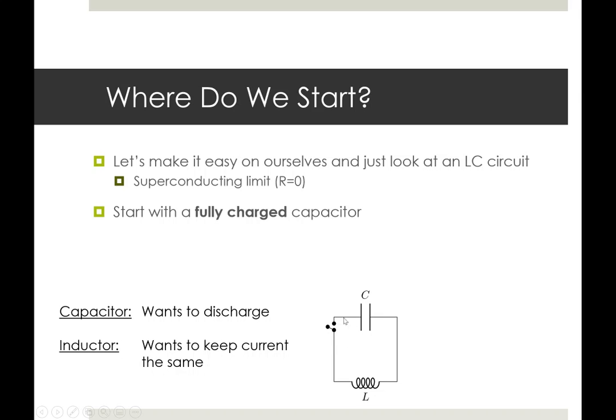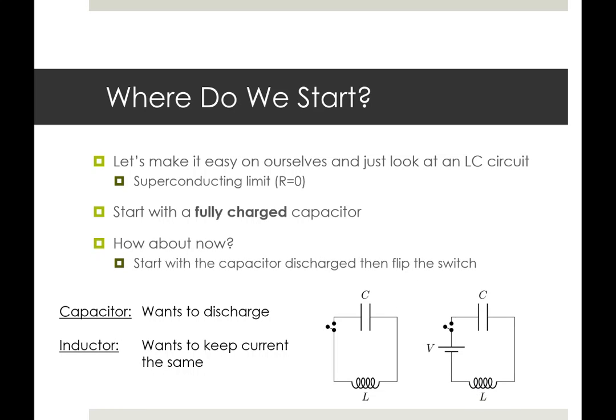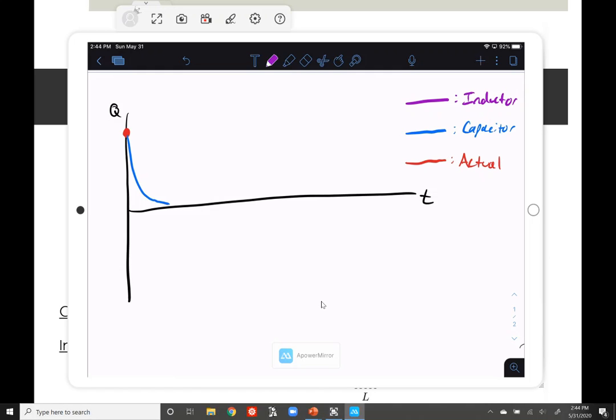Initially, this was an open switch, absolutely no current allowed to flow. So right after closing the switch, it again wants no current. And no current on a graph of charge means keeping the charge exactly where it is.